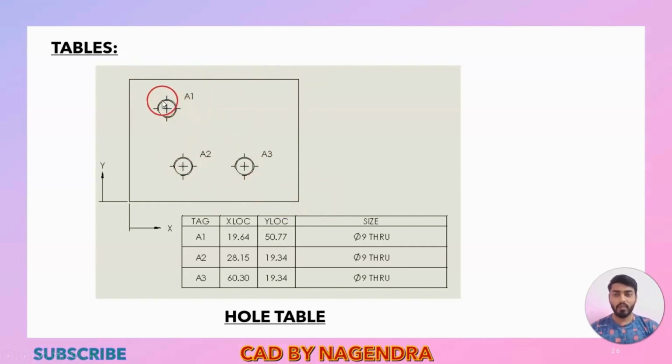So if you want to create one hole, we need to mention here the position, horizontal dimension, how much we are having, vertical dimension, how much we are having, what is the diameter of this hole and what is the depth of this hole. If I mention all dimensions here, horizontal for this hole, again for this hole, again vertical dimension for all these holes in an individual way, all dimensions will get clumsy and we will not be able to read this diagram properly. So in such a case, we will create one tabular column like this.